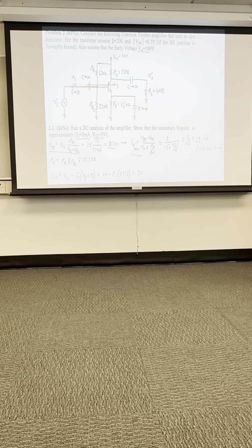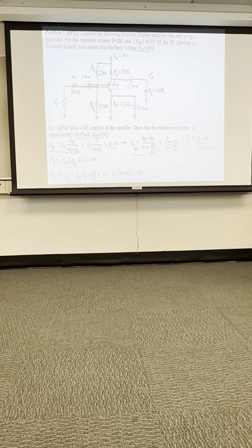So I want to make sure we really understand how, given a circuit like this, it looks very different from the circuit we've been going with. The circuit has some capacitors in it. What's the purpose of these capacitors? What's its purpose? Filter out high frequency. So it filters high frequency. What else would a capacitor function as? Maybe cause the voltage not to drop super significantly.